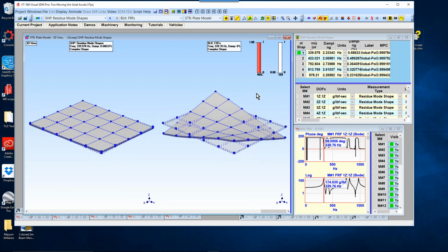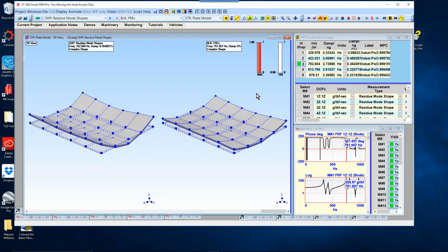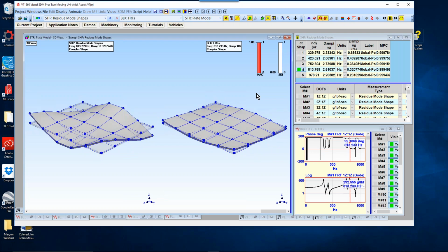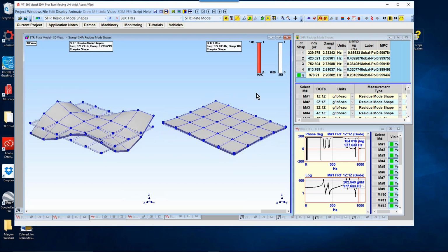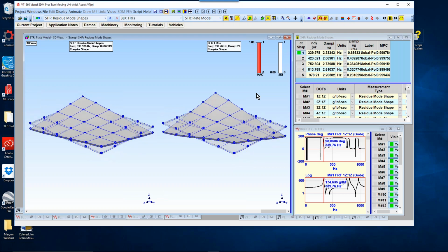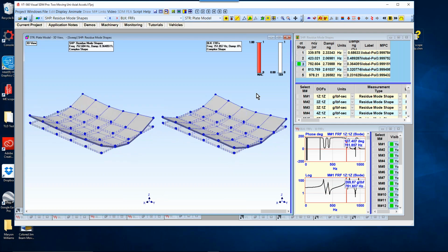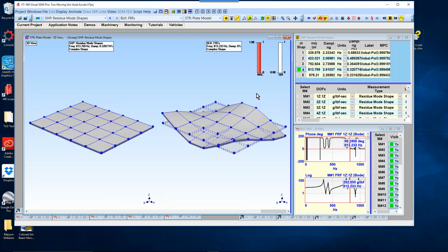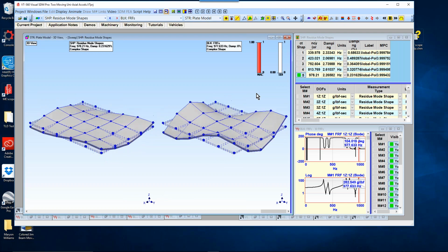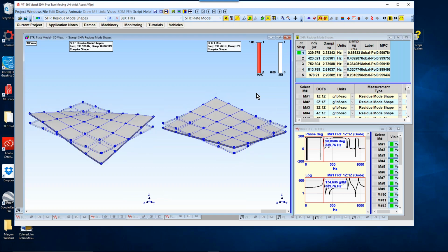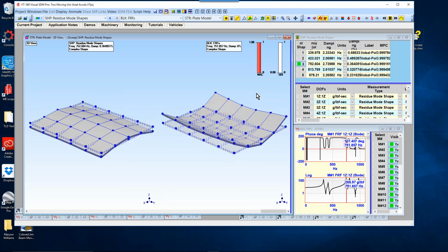The difference between a cross-spectrum set of single reference data and an ODS FRF set is that the magnitude of the ODS FRF is an auto spectrum of each response. So there I can integrate an ODS FRF and I can get the response of the machine in inches per second rather than in G's. And if I start out with a calibrated seed, then I have a calibrated set of ODS FRFs that can be either in velocity or displacement or in acceleration.